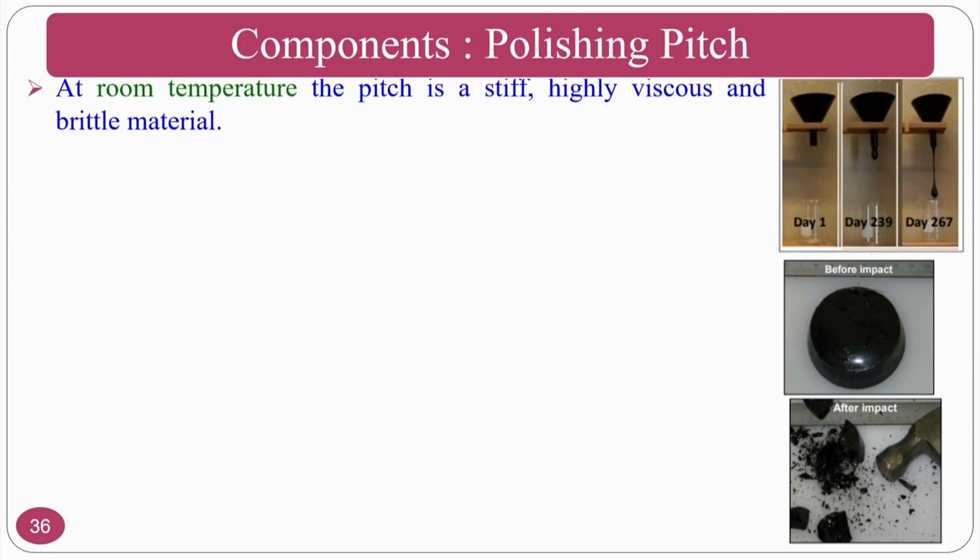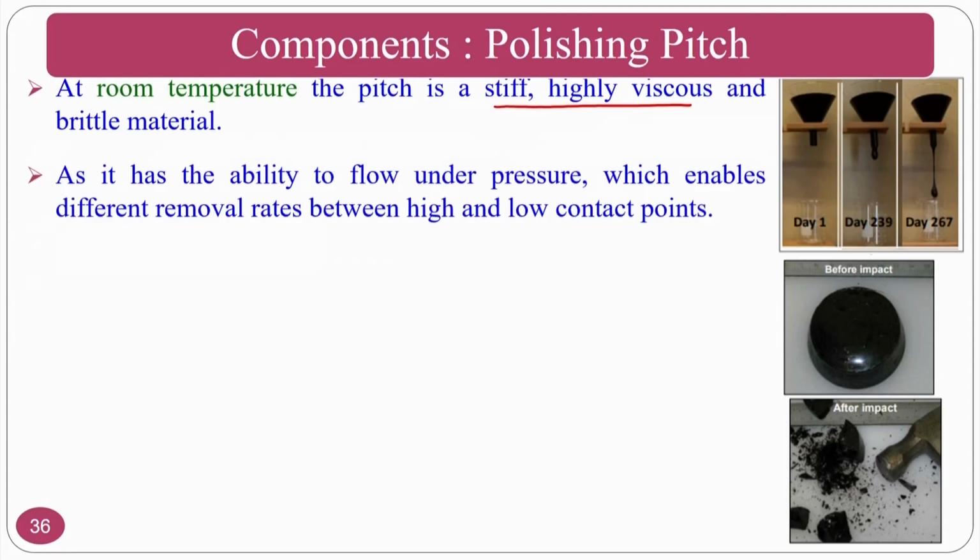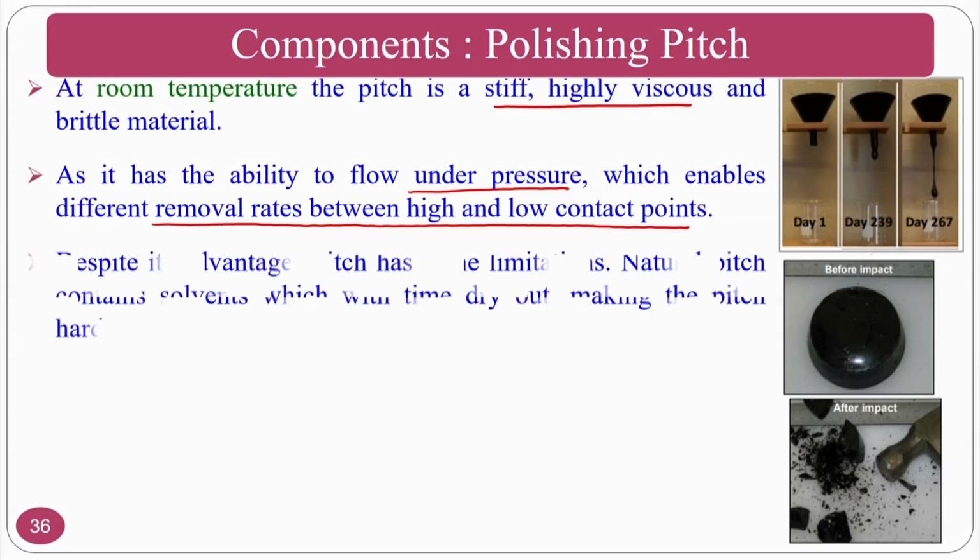If you see, at room temperature pitches are stiff, highly viscous and act as brittle materials, and their ability to flow under pressure enables different removal rates between high and low contact points. Because if you are applying a certain load, what will happen if the pitch is very stiff, very brittle, then it will cause a higher material removal rate.